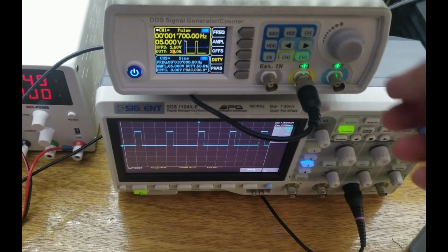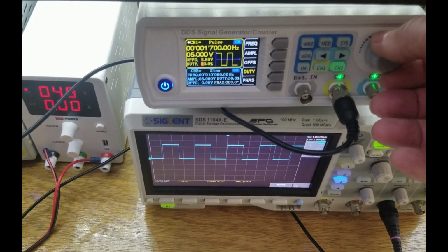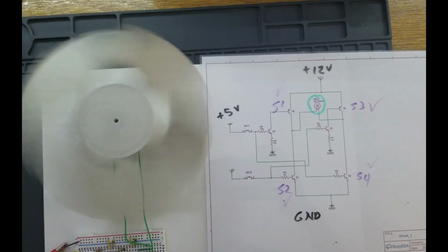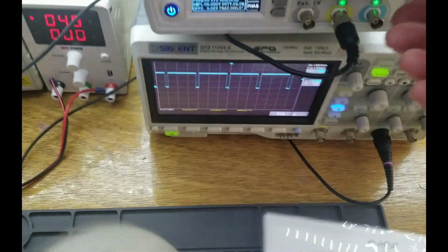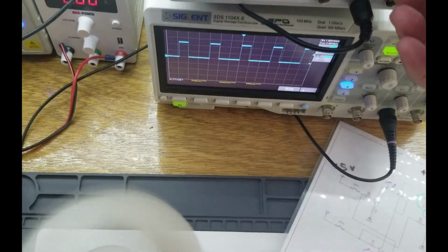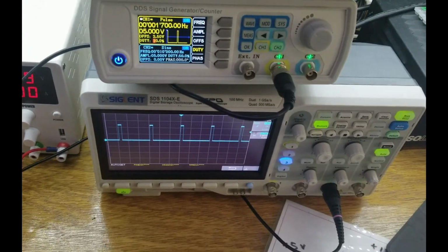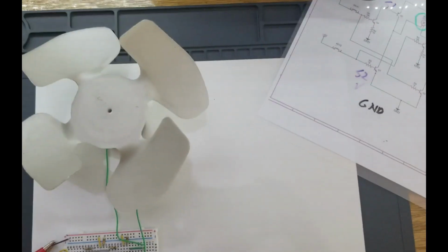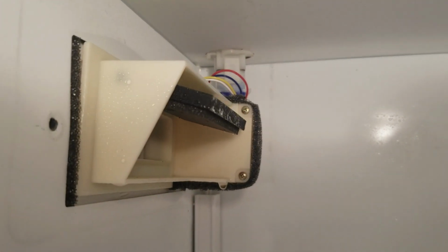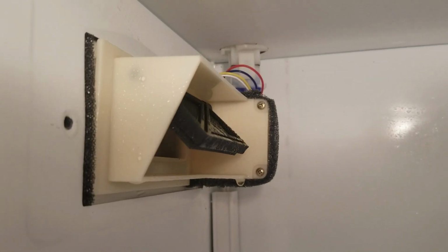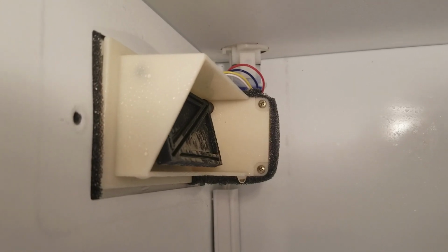If we wanted to increase it to 30, 40, even 50%, of course the motor is going to respond accordingly. If we go more toward 100%, you're going to have full speed. So that's how you can control, with a semiconductor H-bridge, not only the direction, you can also control the speed of the motor. A practical implementation of doing so might be that just before a damper or some type of an actuator closes, that you would want to slow it down for a more gentle closing.